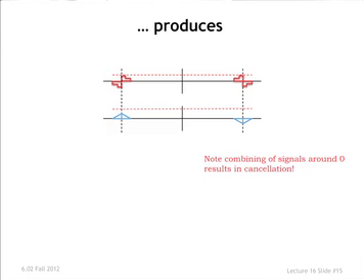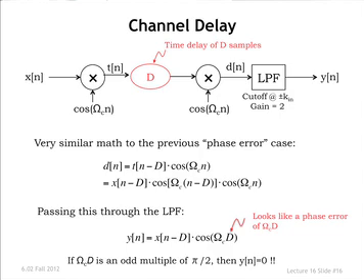All right, so that's the uncertainty between the phase of the transmitter and the phase of the receiver. Here's another thing that has a similar effect, which is an unknown delay on the channel. At the transmitting end, you've got your baseband signal multiplying the carrier. This is what's transmitted. But then you have a time delay, let's say D samples. So what's received is actually T of n minus D, and that's what's going to get multiplied by the local carrier.